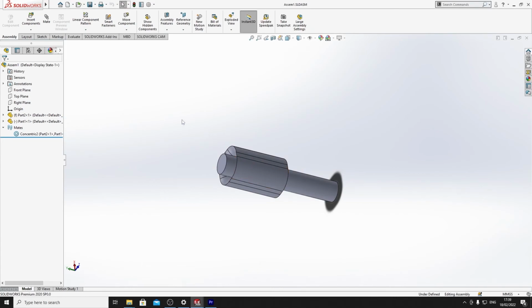Now, sometimes if you do something like create parts within the assembly, you can either save the parts in the assembly itself, or you can save them as individual parts outside the assembly. Now, I would recommend the second step because if you save the parts inside the assembly and let's say the assembly crashes or something corrupts, all your parts are going to be vanished. So it's good practice to save each individual part outside of that in a defined folder that you know its location is not going to change, and so you can bring in parts more easily that way.